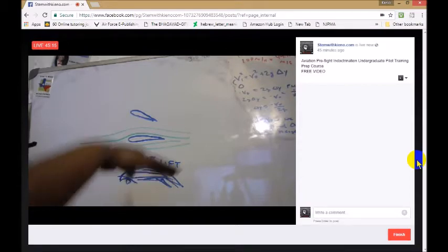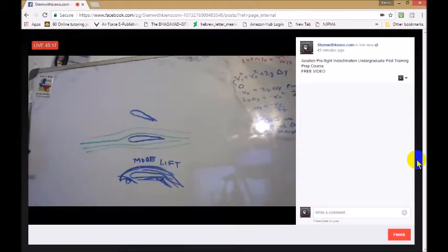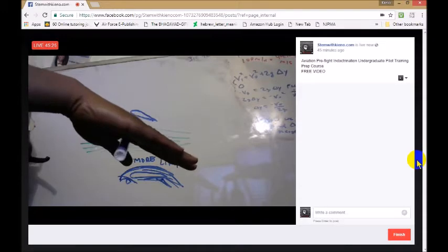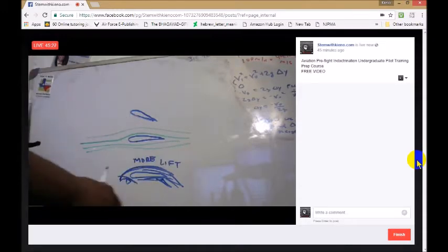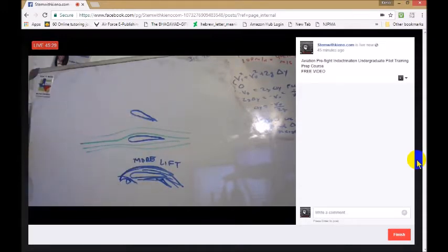Now, when we're landing, can we have our nose pointed all the way up in the air? No. So we extend our slats and flaps so the pilots can see the runway and produce a similar amount of lift at a slower airspeed. These are high lift devices, slats and flaps, and they extend. If you're flying on a commercial flight and sit by the wings, you will see the slats and flaps extend.